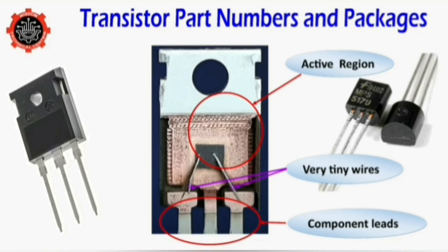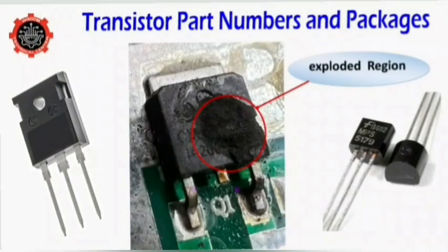That is, removing excess heat from the transistor, because as we know, it is made up of solid state materials or semiconductor materials, where their biggest fault or problem is heat. So if we do not get that heat away from this stuff, it's going to burn and even catch fire. So most packages of the transistors are designed to rapidly pull that heat away from the active region.